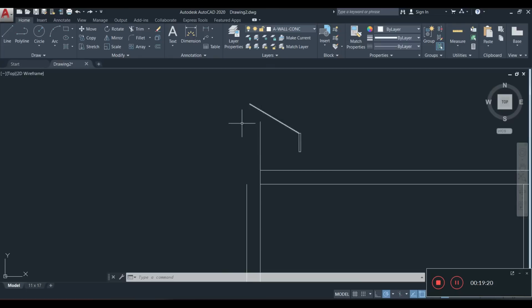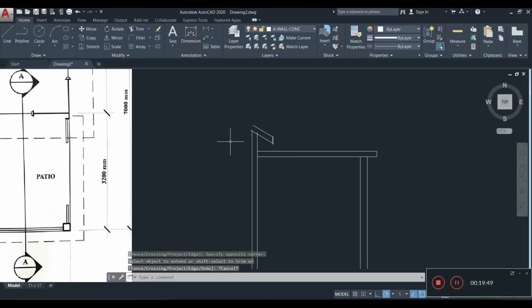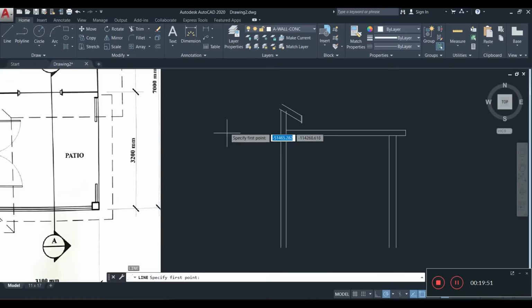So when you did your SBA, if you did an eave detail, that is what is happening at this corner here. So let me do that. 150, and I'm offsetting this line here down like that. That line there will be extended to touch your fascia board like that. Alright, and then now you know your walls will go up to touch your rafter like that. Alright, now given the fact that it came over a bit, I'm going to be extending some of it,